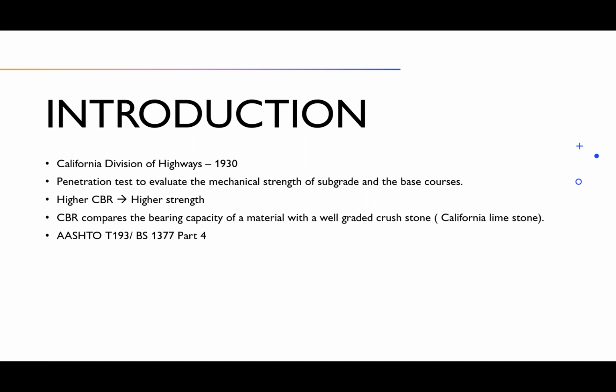This CBR compares the bearing capacity of a material with a well-graded crushed stone, which is a standard California limestone. This test is according to AASHTO T193, or you can use British Standard BS 1377 Part 4.